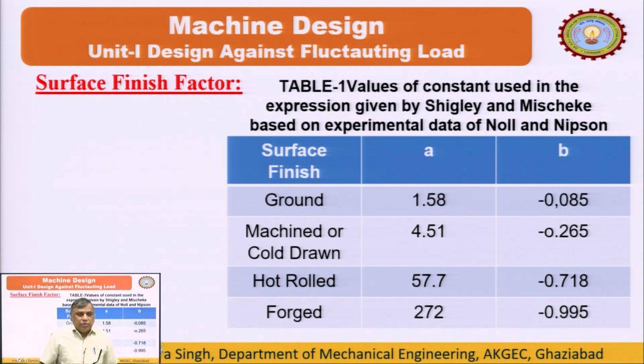When we were discussing the mechanism of fatigue failure, there were two steps: one is the initiation of a crack and the second stage is the propagation of the crack. A surface scratch or hair-like scratch may cause the initiation of the fatigue failure mechanism. So, this is a very important factor which we should use to modify our lab specimen endurance limit.